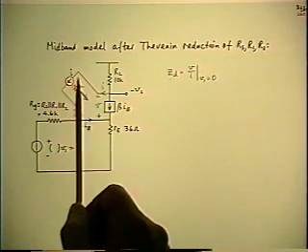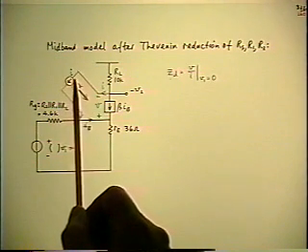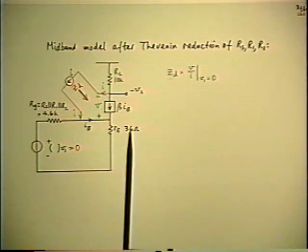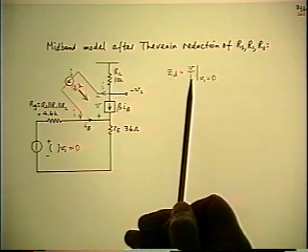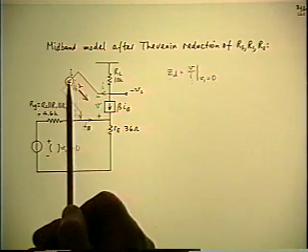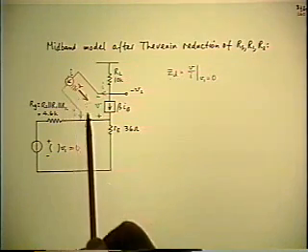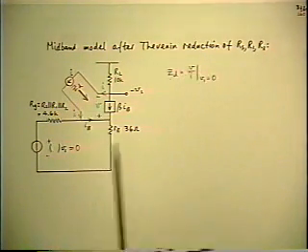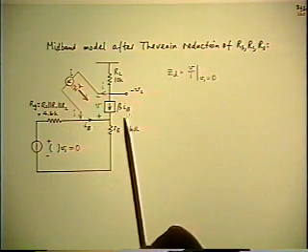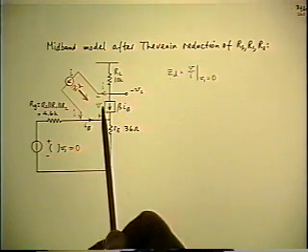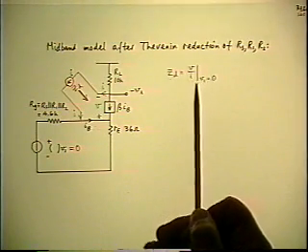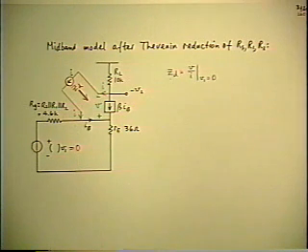I've drawn the independent source as an ideal current generator because, once again, it can be anything you like. Why not make it the easiest thing to do the calculation? Since the denominator is the independent input, I chose an independent current source to provide the test signal. So all I have to do is as little analysis as possible in order to find V as a function of I. Then I can divide the I into it, and what's left behind is the answer I want.